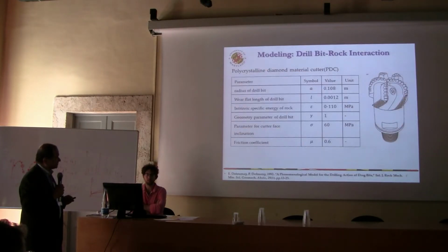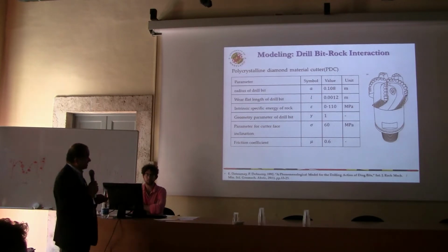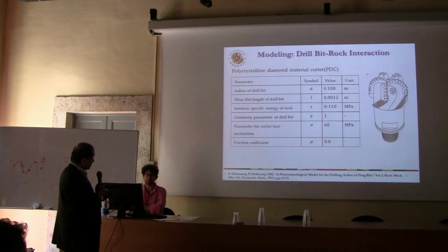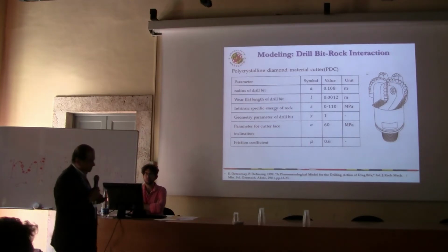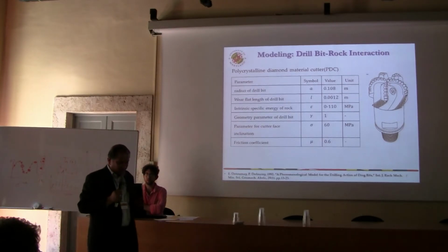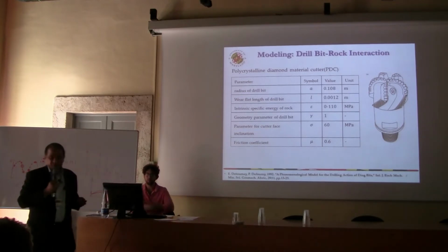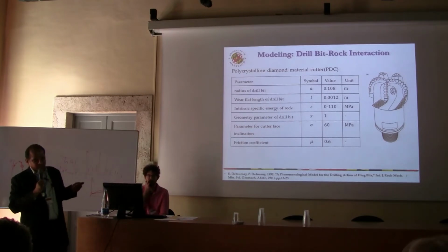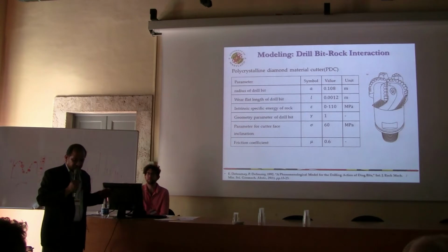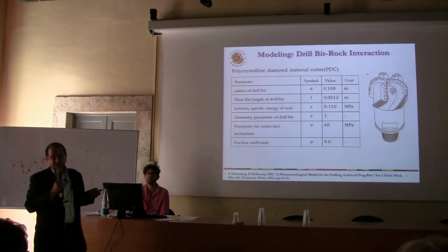Now, throughout the talk, one of the cutters that we use is this PDC bit that you see up here. There are certain parameters specific to the system, like the radius of the drill bit, the wavelength of the flats, depending on the rock that you cut, the specific energy, the geometry around the drill bit, the cutter force inclination angles, and the friction coefficient. Of course, these models are not new in this work. They've been used for more than 20 years. Emmanuel at the University of Minnesota has been working on these models for quite a number of years, so those are the same models that we use here. What is new in this work is how we model the dynamics and the bit-rock interactions.